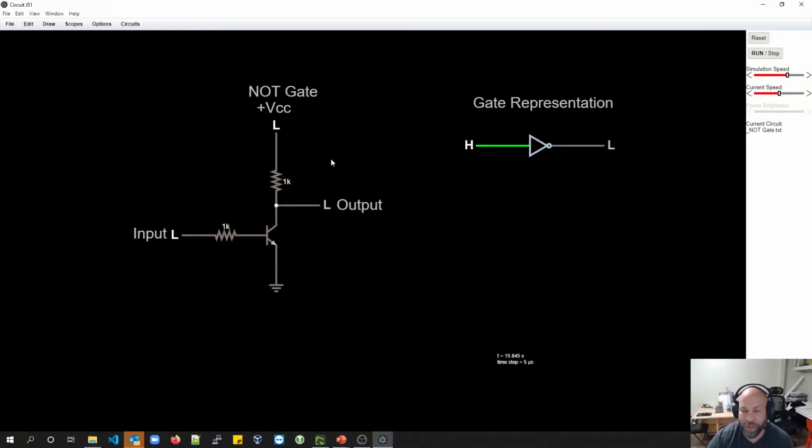And to give a demonstration of how this works, even though you'll only see the schematic representations, these symbol representations in schematics, here's our VCC, our voltage coming in. There's the resistor drawing down the current, and if the base is not energized, then the voltage will go through the line towards the output. But if we turn the base input on, energizing the base, then it will, of course, pull the voltage down to ground, making the output a logical low, or a zero.